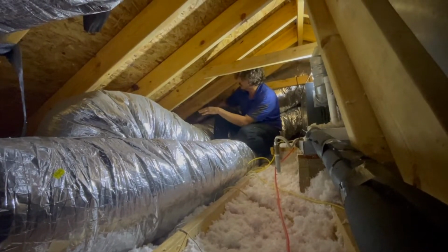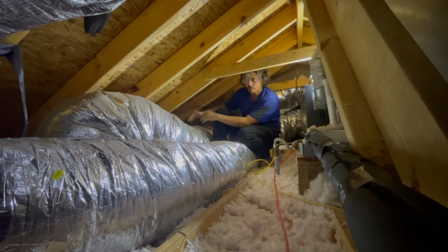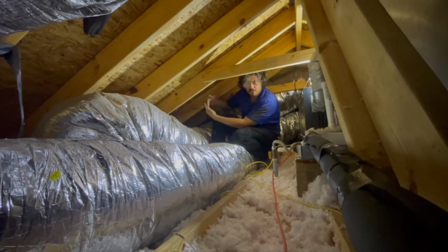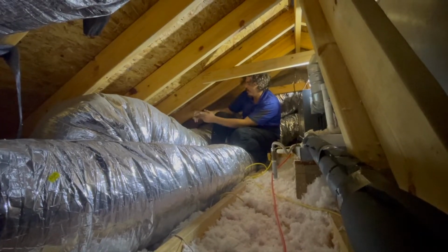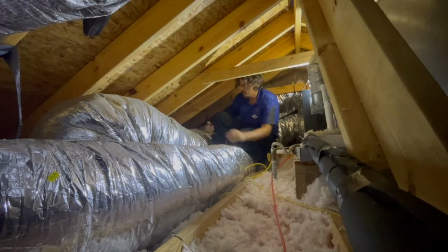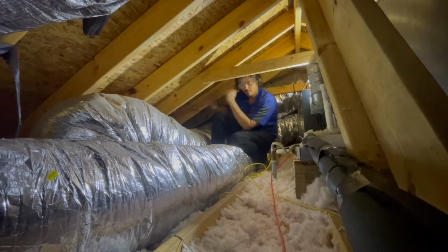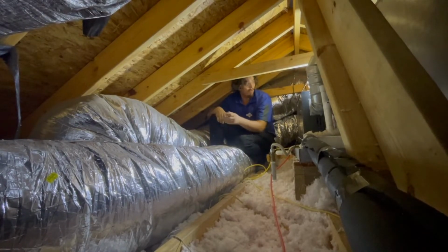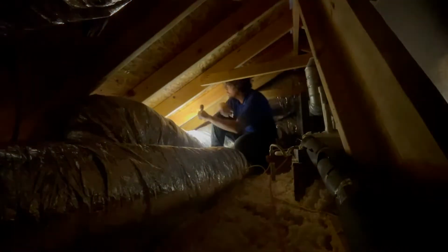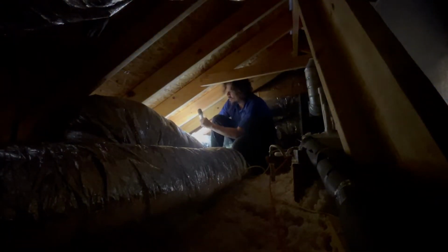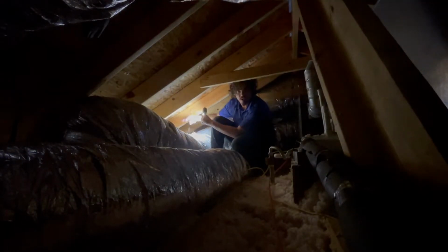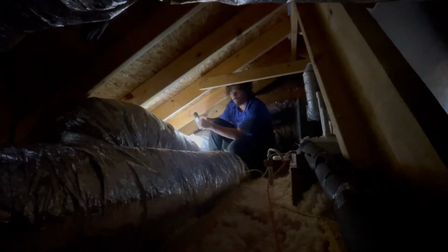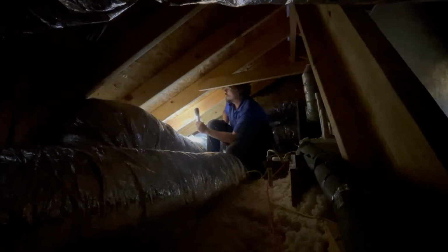There's no insulation around the perimeter of this building because they didn't put the proper insulation down or roof soffit connection. So all the insulation can either fall out or get blown inward. In this particular case, it looks like a little bit of both, but that's going to cause the backside of that drywall to be very hot and humid, and the inside drier, which is potential for all kinds of moisture related fun.